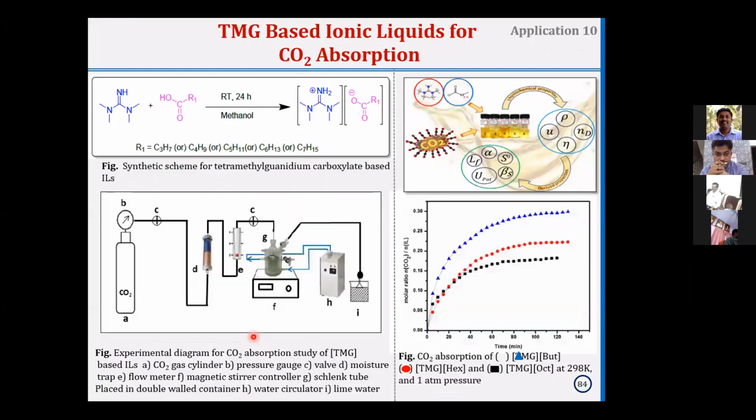And in the literature, we are also working on carbon dioxide absorption. This is compared to the conventional system where we use monoethanolamines, and the same process where you convert amine to amine and then extract, more or less the same process, but ionic liquid facilitates. And we all know that absorption is easy with the simple conventional monoethanolamines. The high cost at industrial scale is for desorption. So can we address the desorption issues, or can we recycle or reuse this ionic liquid, if not recycle, n number of times and facilitate this? Anyway, this work is in progress.